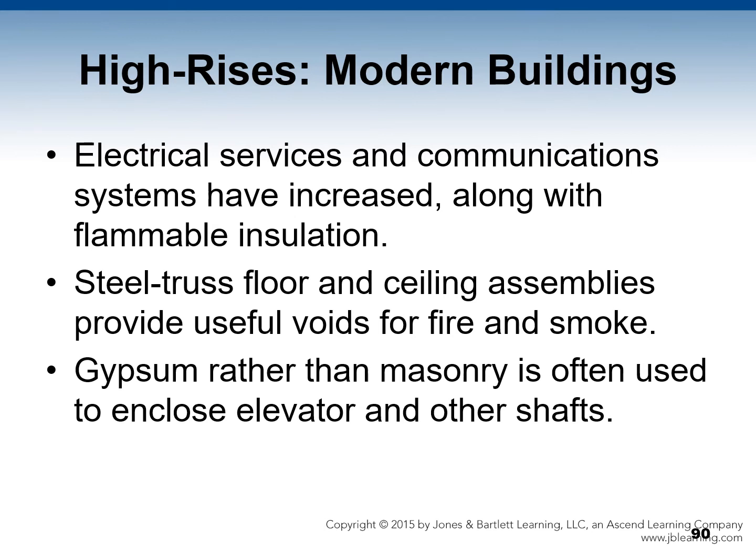One case example: a firefighter was seriously injured by falling glass in the One Meridian Plaza fire in Philadelphia. This is a really famous fire. You need to look it up and read about it. Breaking glass is extremely hazardous because glass pieces can travel for several blocks. Energy-efficient windows resist failure in a fire and eliminate the ventilation provided by the heat-caused failure of single-pane sashes.